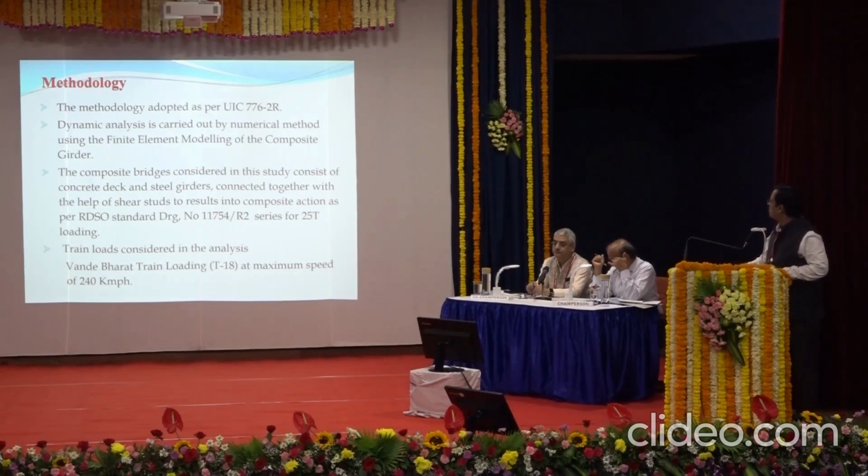This is a very new topic, no IRS standards are available, so we took up the methodology adopted as per UIC 776-2R. Dynamic analysis is carried out by a numerical method using finite element modeling of the composite girder. The composite bridges considered in this study consist of a concrete deck and steel girders. They are connected together with the help of shear studs, so they act compositely, because it's a composite girder.